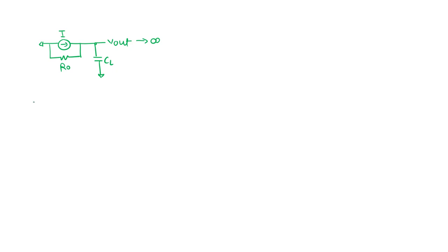One thing is R out, and C out is the other thing. Directly, these are the effective values of resistance and capacitance at that particular node. So my time constant is nothing but R out C out, or R effective C effective. Then we can directly write omega P is 1 upon R out C out.